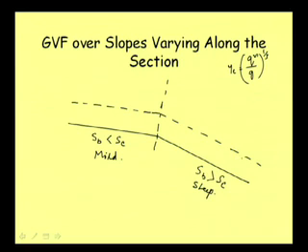Say this is yc, this is yc. Okay. Then let us think about the normal depth. What will be the normal depth? That we can see here, it is mild slope. So, our normal depth will be greater than the critical depth. Okay. So, normal depth line will be somewhere here. This is say NDL, normal depth line, and we can say that this is our YN1.